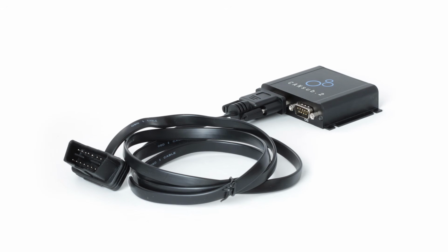But in many modern cars, the access to the raw proprietary CAN bus data is going to be deliberately blocked by the manufacturer through the OBD2 connector. And that means you are still able to use the OBD2 connector to get your reference signal, and you can do that through, for example, channel 1 of the CANsub.2, but then you need to get access to the proprietary raw CAN bus data from another source.